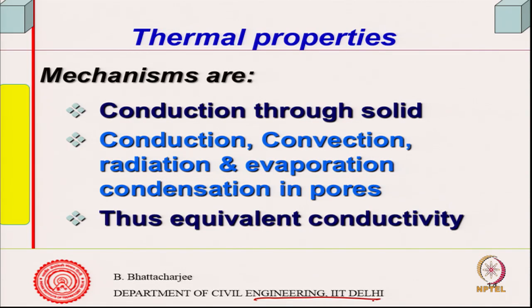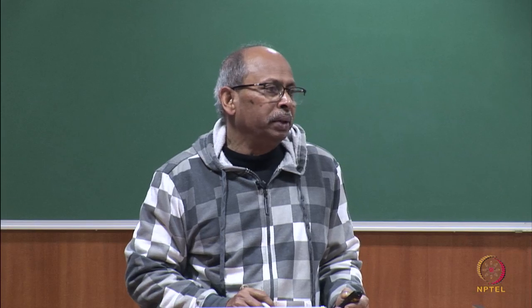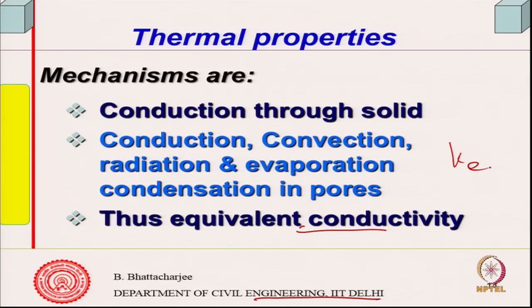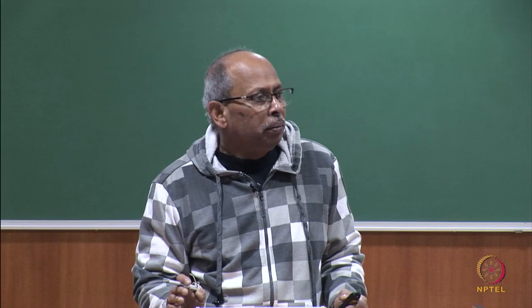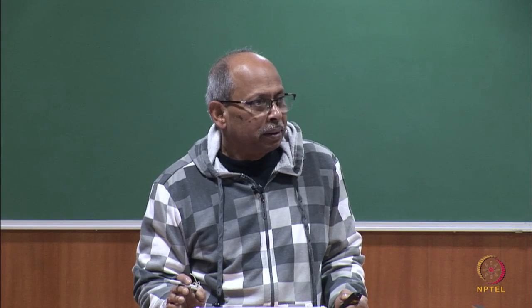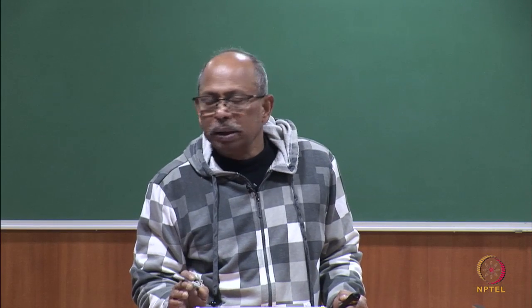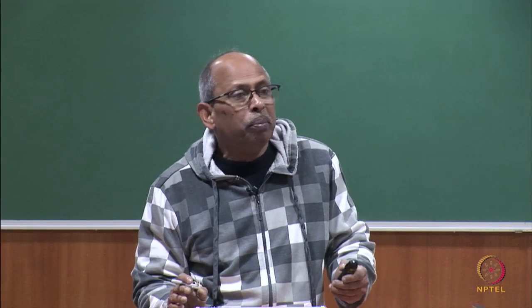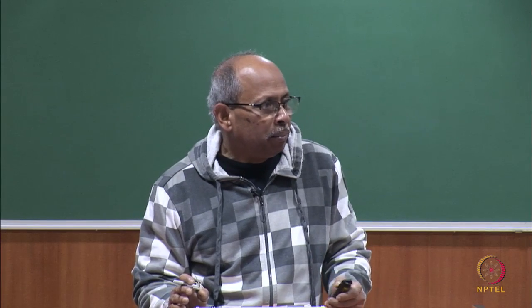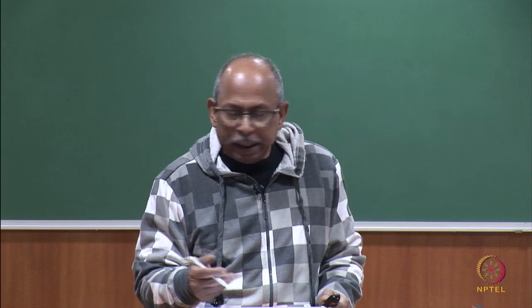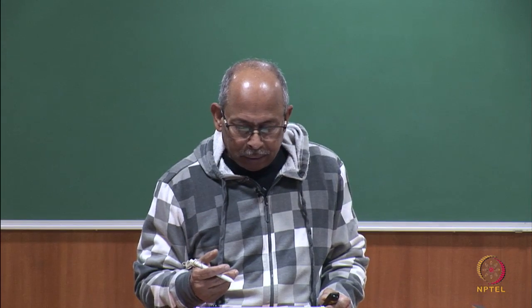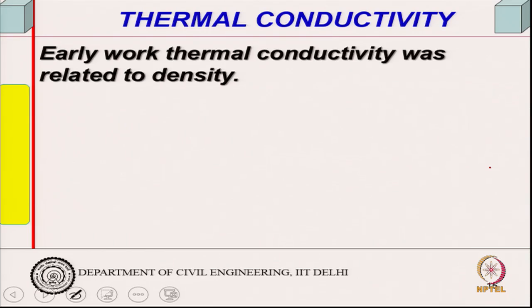So, what we talk about in the case of porous material is an equivalent thermal conductivity of such material, Ke. Most of our materials, brick, concrete, lightweight concrete and similar ones, are all porous materials. Even timber is porous, and insulating materials are deliberately porous. If I understand the mechanism, then it becomes easier to look into that. Since it is a function of porosity, higher the porosity, conductivity will be low.